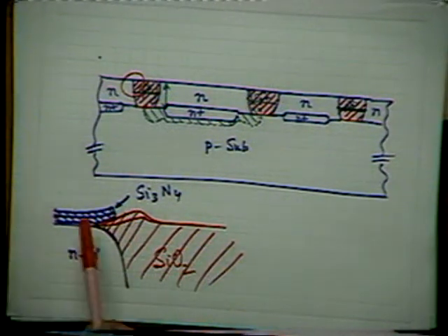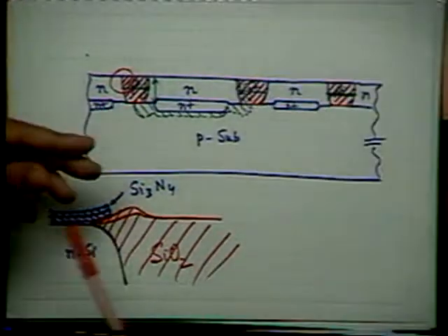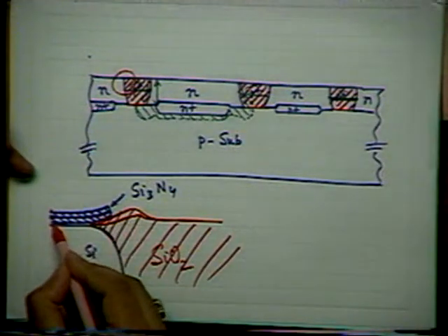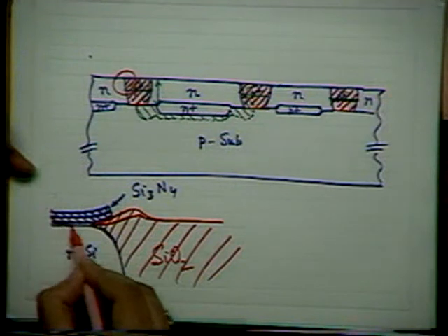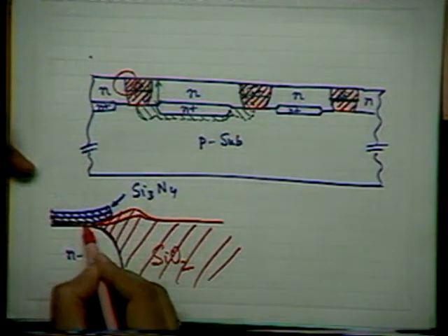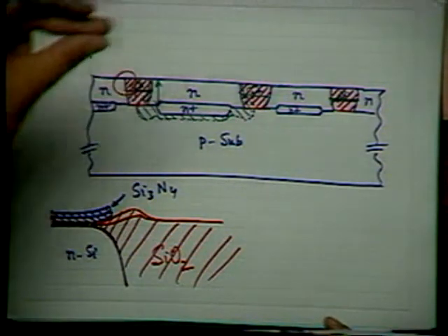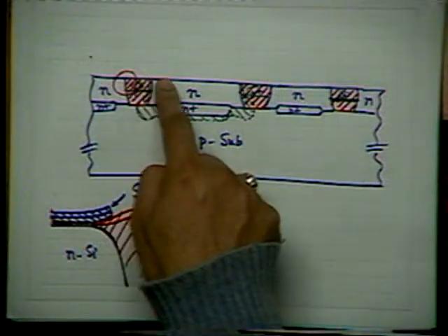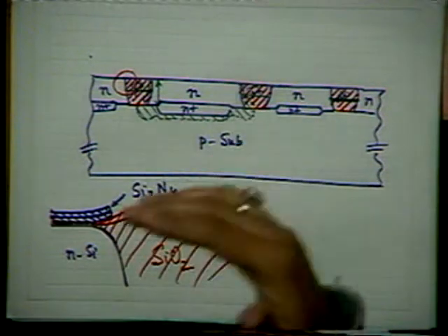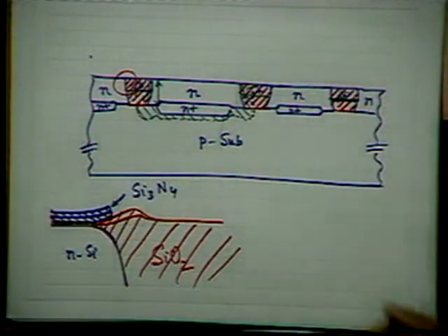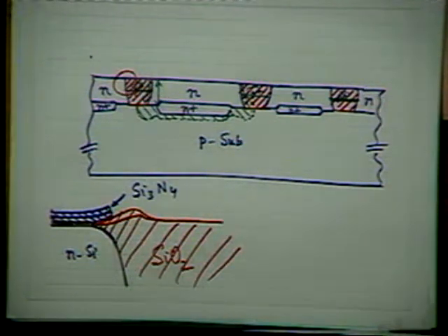Normally below the nitride there is a very thin oxide film kept. I'm not discussing the details of technology. Actually, what is done in this process is initially you have a very thin oxide film grown, and then thereafter you deposit a nitride film, and then do that oxidation.